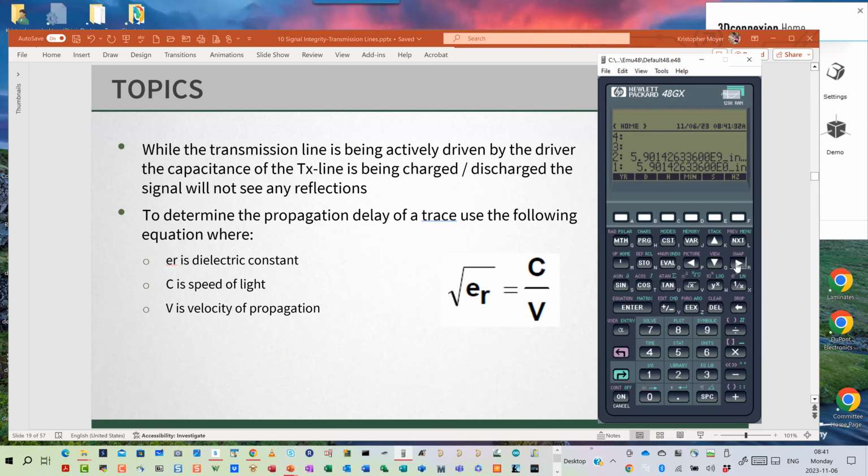Okay. I'm going to do the same thing here, but what if I was 100 picosecond? So 0.1, I went from 6 inches to half an inch right here, approximately, right? So just by changing that rise time to the faster and faster rise time, now this means that my digital signal that used to be able to travel 6 inches on my board with little to no signal integrity issues, reflections, or anything like that, now it can only travel half an inch.